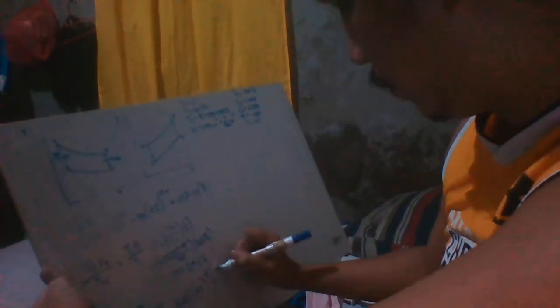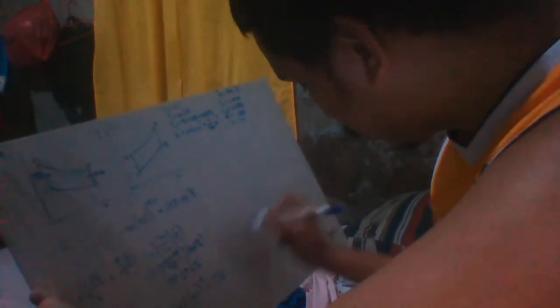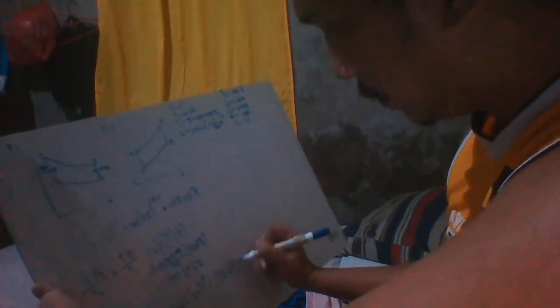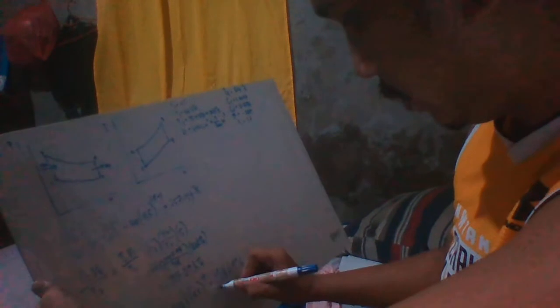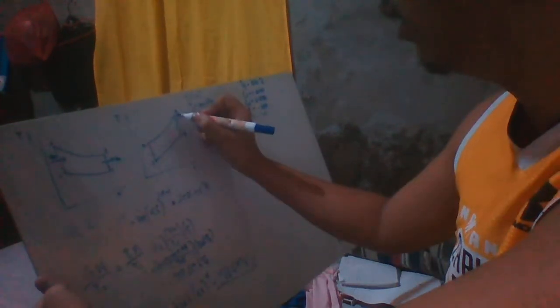So 800 times 9.5 raised to 0.4, we will have an answer of 1968.69 Kelvin. So this is our highest temperature, T3, according to our graph.